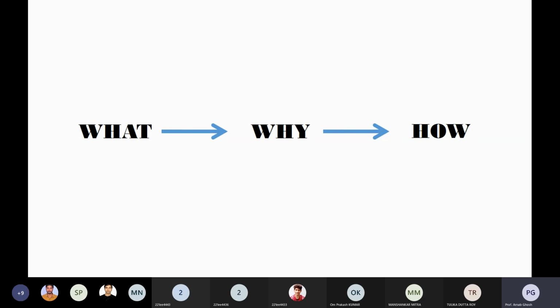What will be the basic structure of switching converters, what are the different modeling techniques of the switching converter, why that modeling is also important, and how the controller will be designed. And for the magnetic circuit, a normal ferromagnetic core we are not able to design for, so we have to consider a ferrite core. The range of switching frequency is based on the data sheet, and we design everything accordingly. I think all of you understand the motivation of this subject.